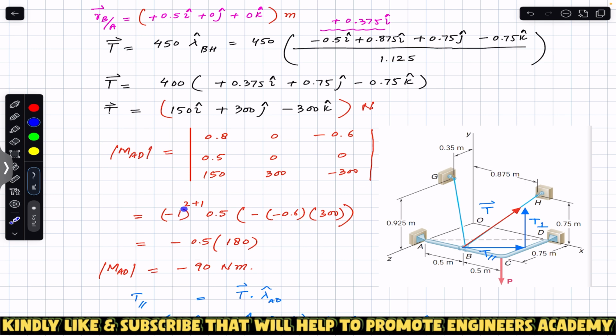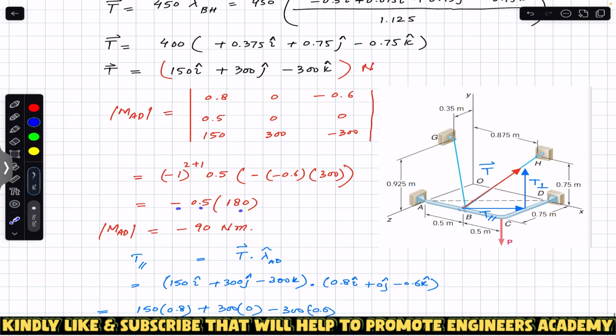So while finding the determinant, we must write minus 1 to the power, since this 0.5 is in second row and first column, so minus 1 to the power of row plus column, so 2 plus 1, then 0.5, then hiding this row and this column, so 0 times minus 300 is 0, and minus minus 0.6 times 300 gives us 180, and this minus 1 to the power 3 is minus, so minus times 0.5 times 180 gives us minus 90 Newton meter.